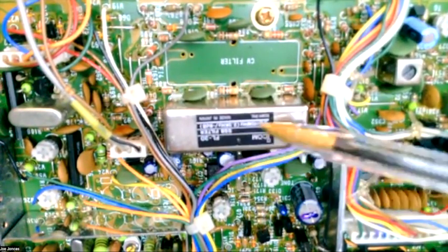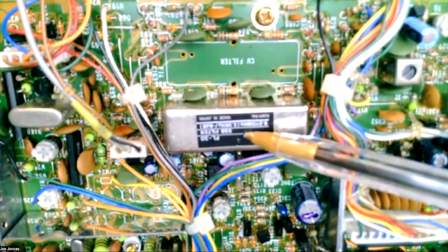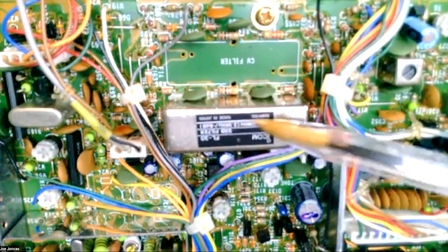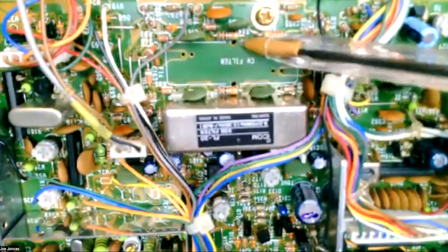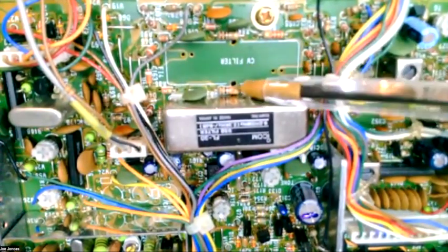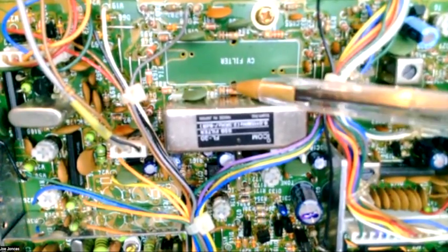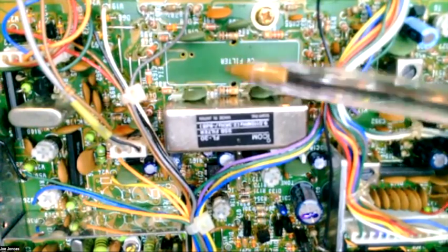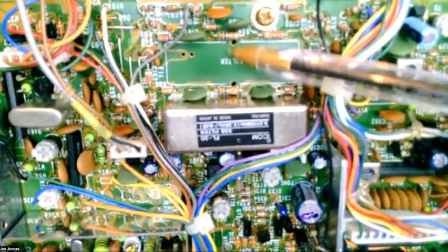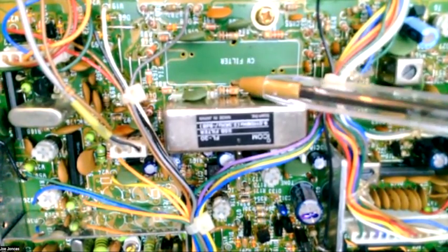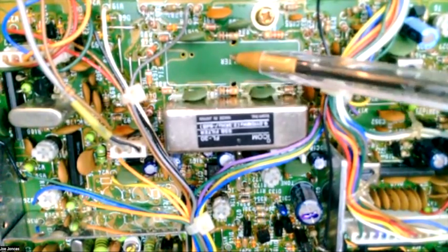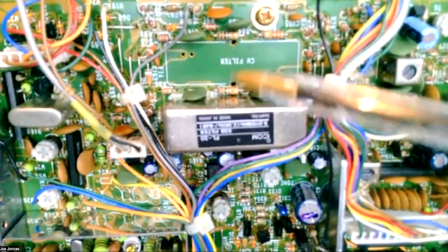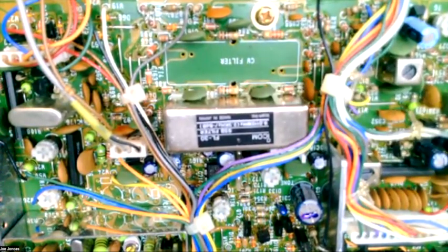What this does is allow probably about a 2.7 kilohertz signal bandwidth to go through. And then here's a CW filter, and normally they're about 500 hertz. So you can eliminate a lot of CW. And by the way, the narrower your filter, the better your signal to noise ratio, so you can get a lot weaker signals if you have a CW filter. This one does not.